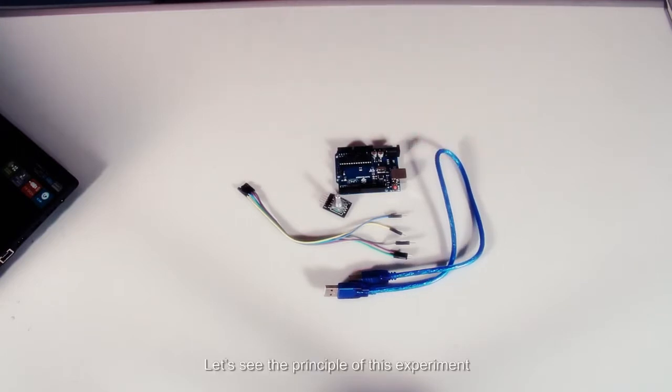Let's see the principle of this experiment. There are two main types of rotary encoder, absolute and incremental. Here we use an incremental encoder. An incremental encoder is a rotary sensor that turns rotational displacement into a series of digital pulse signals, which are then used to control the angular displacement.